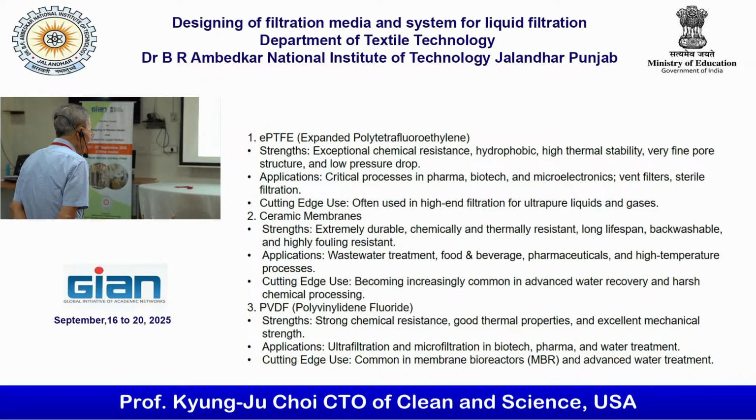PVDF, this is quite an important one. Even though it is a solution casting material, it's quite a popular material because of the strength, chemical resistance, good thermal property, excellent mechanical strength. Application: ultrafiltration, microfiltration, pharma, and water treatment. Commonly membrane bioreactor, MBR, we talk about it, right? It uses the PVDF membrane. Later on, probably they might replace it with expanded polytetrafluoroethylene, the EPTFE. I strongly believe that's going to happen really quickly.